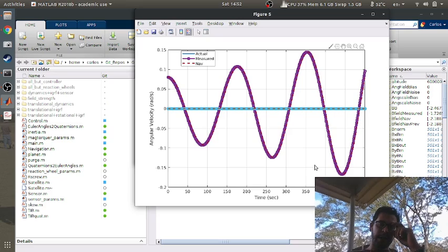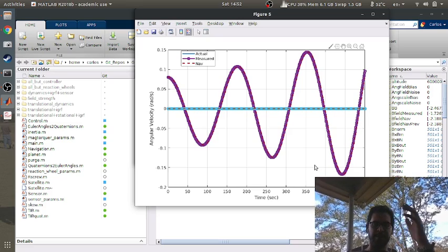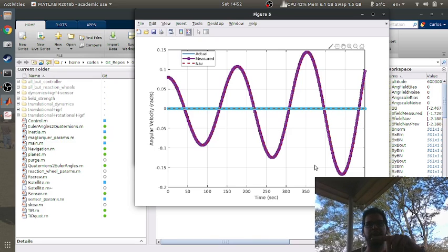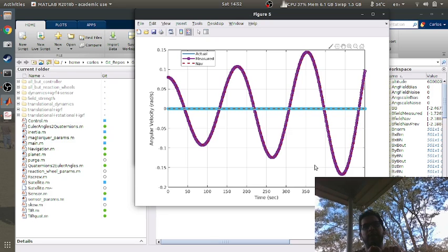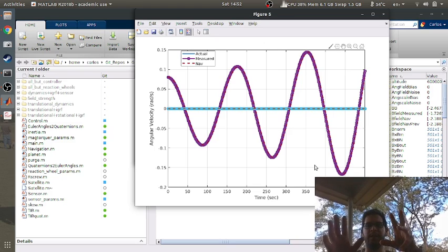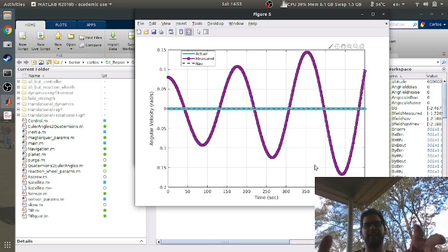Okay, folks, I figured it out, and unfortunately it's no easy fix. So here's the problem. If you're familiar with transfer functions, the transfer function of this system is 1 over s squared. When you apply proportional control to it and you do a feedback controller, you basically have 2 poles at the origin. And when you increase your gain, you're basically doing derivative gain on it, which throws an s in the numerator. But anyway, the bottom line is that you're basically applying proportional control to a double integrated system. And if you look at your tables from introductory controls, that system actually goes unstable.